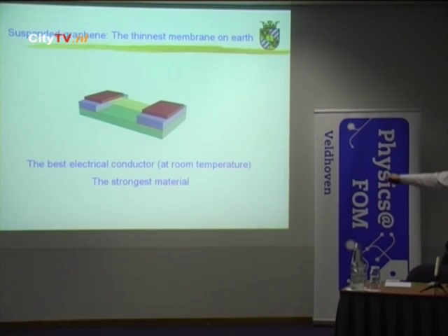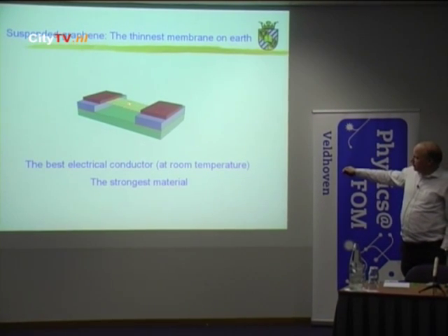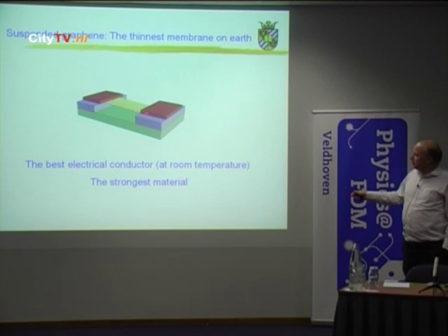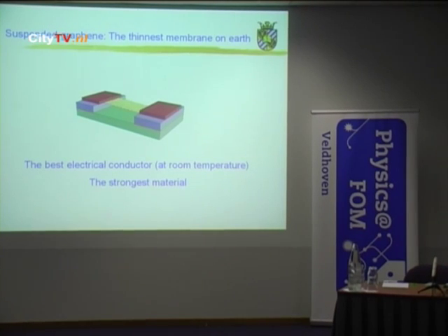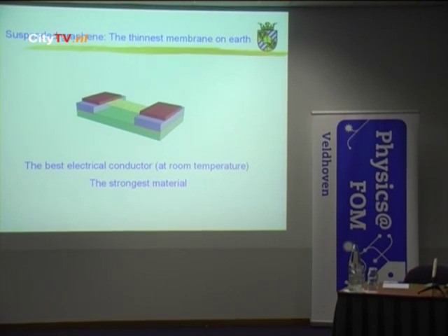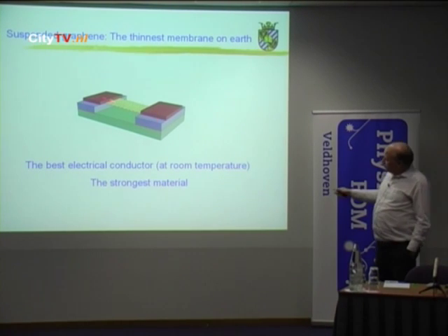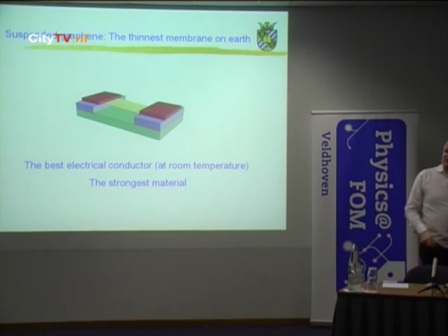So what you do is you pass a very high current between there and there. This is another property of graphene. It's a very good electrical conductor. It's also very rigid, so you can achieve very, very high temperatures without the graphene disintegrating. But what happens with all the other junk? It disappears. Well, it evaporates or whatever. This is called current annealing. In that way you can really make a graphene layer which is almost ideal.